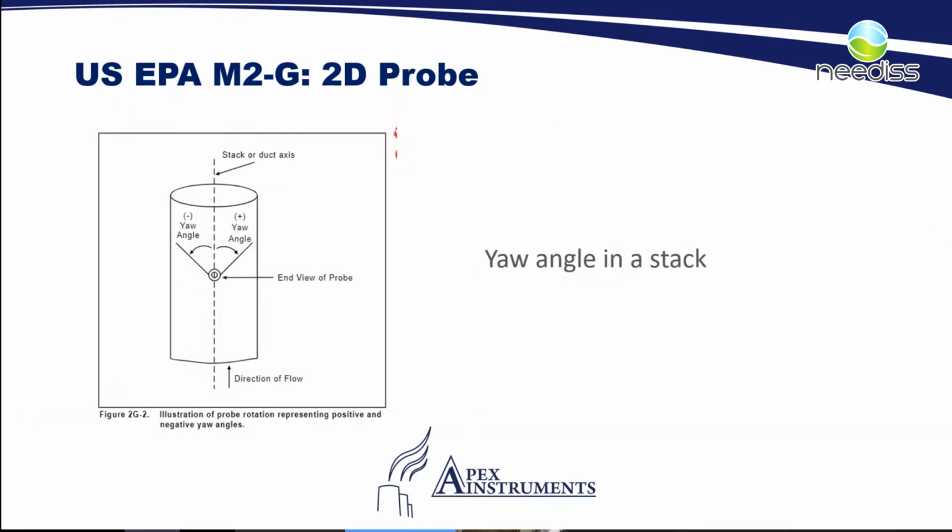So you can see here in our image the end view of the probe, where the probe is pointed directly into the stack there in the middle, and the flow is coming up that stack. Our yaw angle will be negative to the left if the flow is left, or positive yaw angle to the right. So I hope that kind of helps explain what would be considered a yaw angle for this method 2G probe.